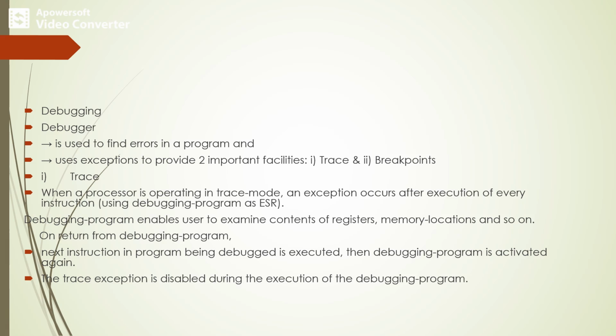The first one is trace mode. When a processor is operating in trace mode, an exception occurs after execution of every instruction. This uses the debugging program as the exception service routine, which enables the user to examine the contents of processor registers, memory locations, and so on.